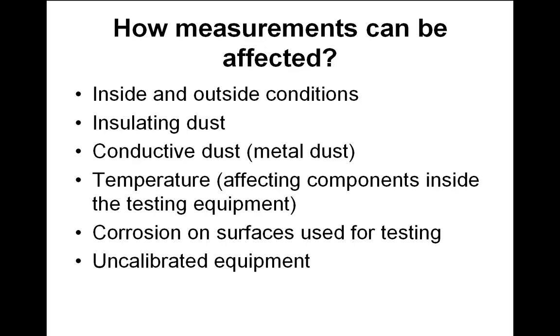And how do you know it? It's a problem as well. You may have to get a standard voltage, which is used to then calibrate the meter, and then you take the meter and you measure the voltage from the insulation tester to make sure that it goes up to 500 volts. I mean, that's one of the things.